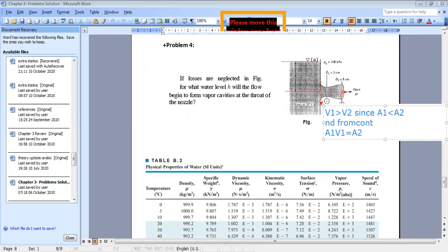So we can say that in our duct, the critical location is 1, because here we will have the lowest pressure. So the pressure is minimal at location 1. This is why we should avoid reaching the vapor pressure at this location. Okay. Now, how do we get the expression of this pressure?